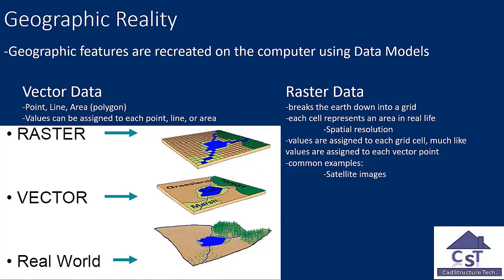The raster is basically the image, possibly the satellite image, or the old map that you want to load to your map, or particular pictures that you want to use as a base map for something that you want to do. Or, let's assume your old building plan is coordinate related, and you want to overlay it on an existing place, to transfer it to the real location where the building is supposed to be located.